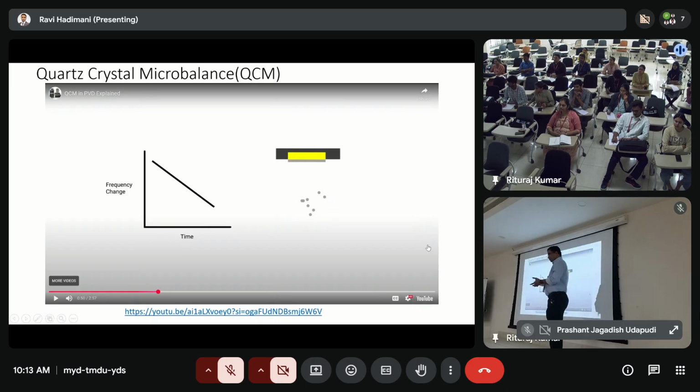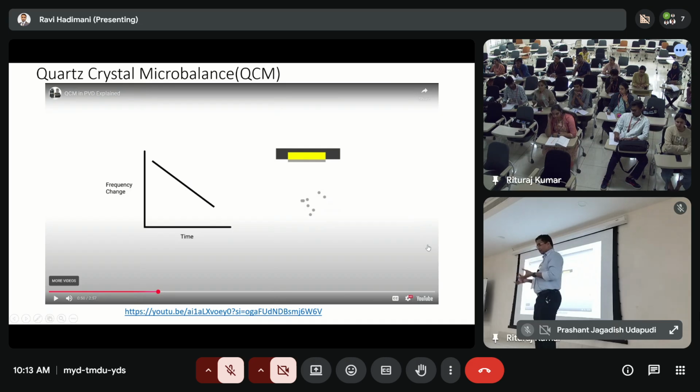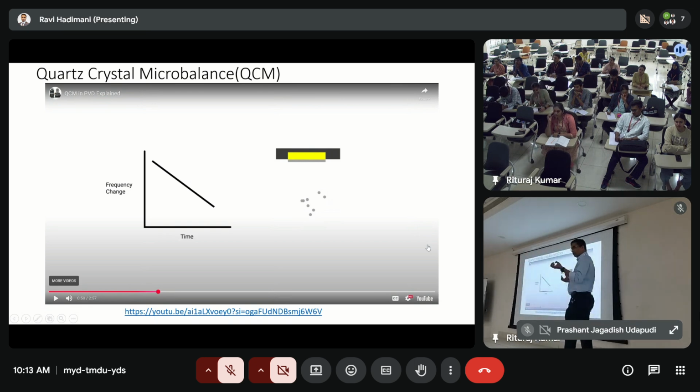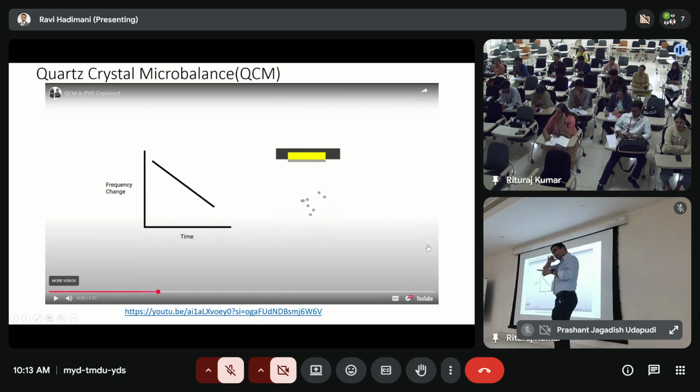And we don't have good control over when you start, for both e-beam evaporation and thermal evaporation, because once you heat, the atoms start to get ejected from the surface, and you can't control that because it is a difficult process to control. But what you can do is put a shutter on top of the target, so whatever vapors are coming do not go to the substrate. But when do you want to press that shutter?